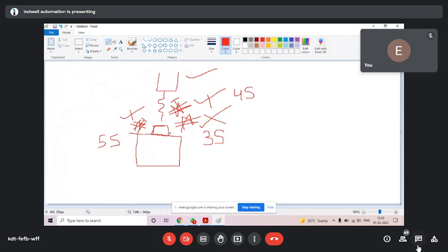First, keep the metal here. So we put one metal sensor, that is an inductive proximity sensor. As the metal job comes on the workstation, this sensor will turn on. And we don't need any push button even. As we put this metallic job here, it will take 1 second. In 1 second, this valve will turn on itself.